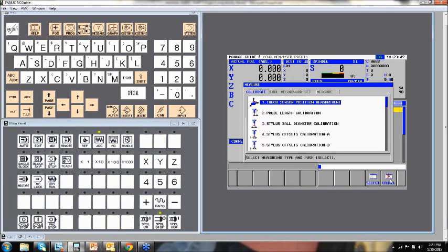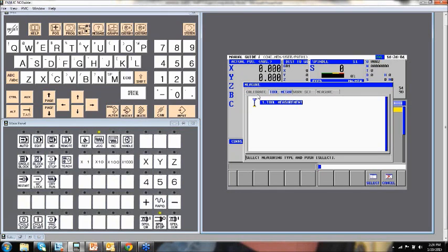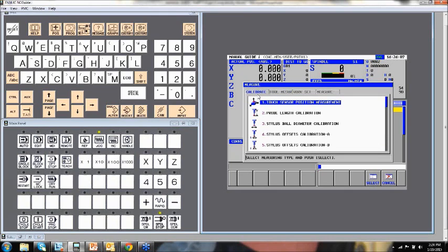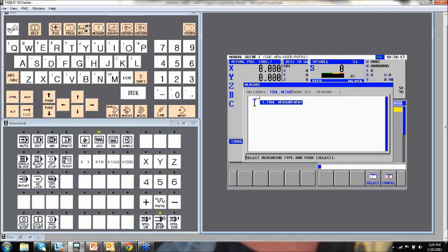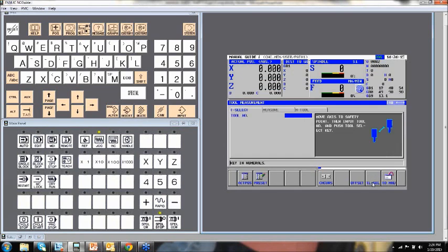That gets us through tab 1, just the calibration cycles. But you have to go through these before you go on to the others. If we go to the next tab, where we do tool measurement, and we hadn't gone through this touch sensor measurement, it wouldn't work. So we'll go into our next tab. This is tool measurement, and it can be for either a lathe or a machining center. You give it a tool number and the direction it's going to measure, whether it's X, Y, Z, plus or minus.